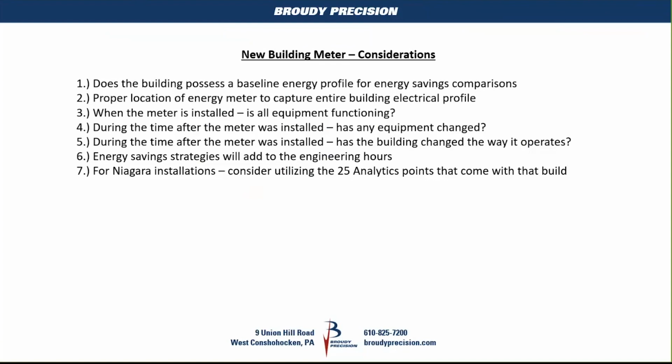You're going to have better energy savings. And a lot of times the energy bills start going up, not down. That's because the contractors that go into these facilities start finding all of these pieces of equipment in various stages of disarray. Some equipment isn't running. Some equipment, you've got a 2x4 stuck in the outside air damper. All kinds of different things will cause the building to now consume more energy.